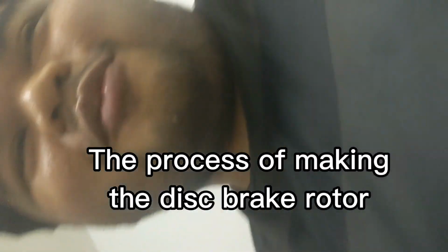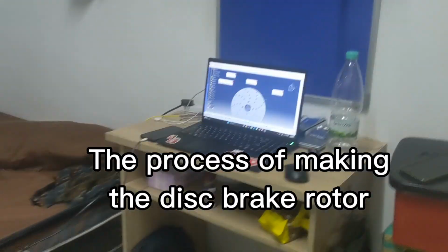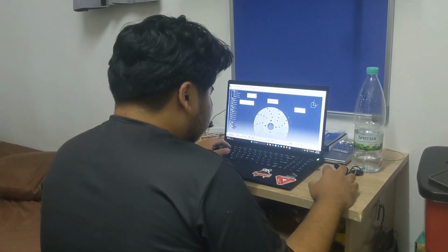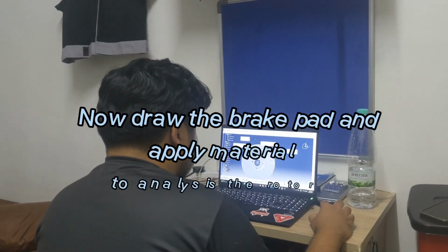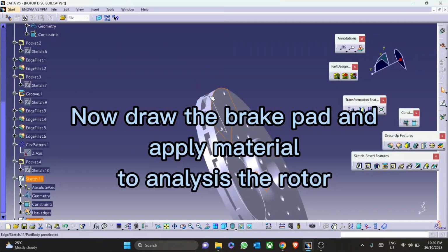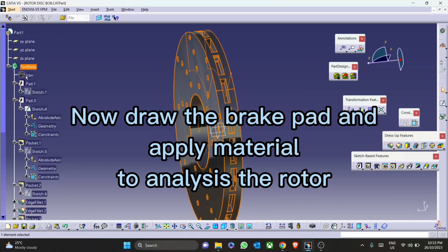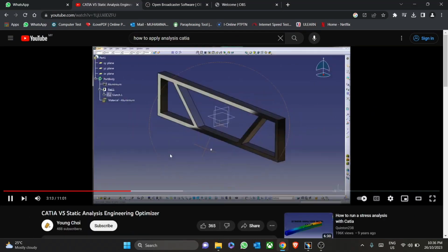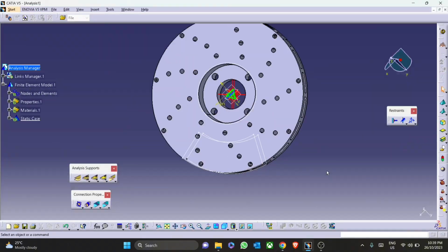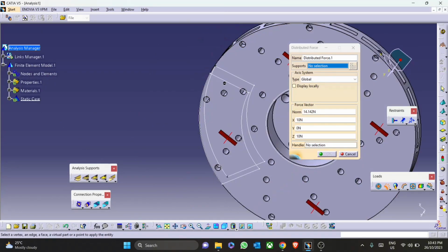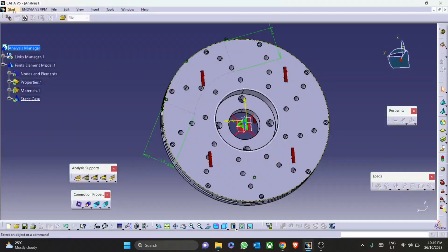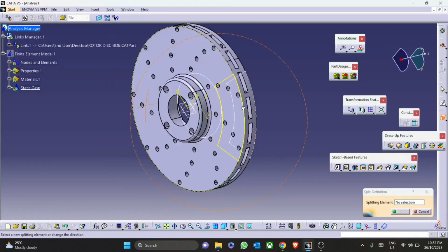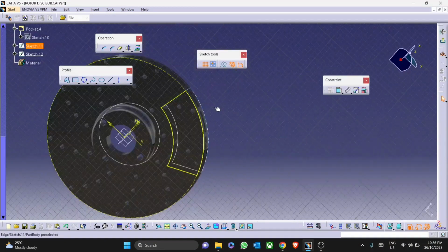Alright, so for the introduction, the disc brake has a metal disc or rotor instead of a drum. It uses a pair of flat-lined shoes or pads that are forced against the rotating disc to produce braking. The pad is held in a caliper that straddles the disc. The caliper has one or more pistons, with a seal and dust boot for each. During braking, hydraulic pressure behind each piston pushes it outward. This forces the pad into contact with the disc. The resulting frictional contact slows and stops the disc and wheel.